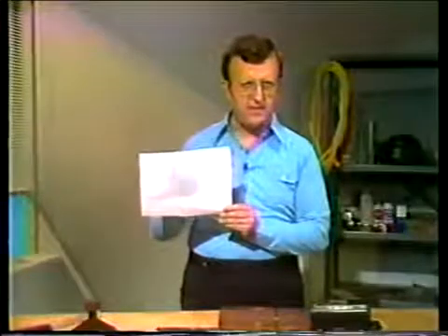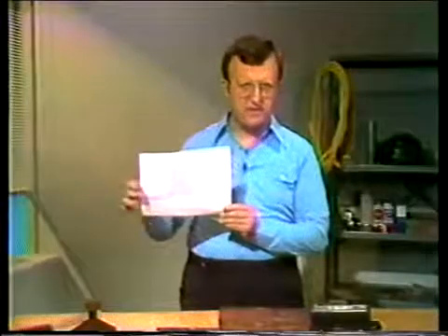Look for discoloration of the tube to find baked-on sludge. Oil can also discolor a metal surface by leaving black deposits there. If no discoloration is seen, make a second check by rubbing a piece of paper on the metal surface. Now, this is the same procedure we used earlier when we talked about the drum and moisture separator. Hold the paper up to the light. The paper will be stained if any oil is present in the tube or header.